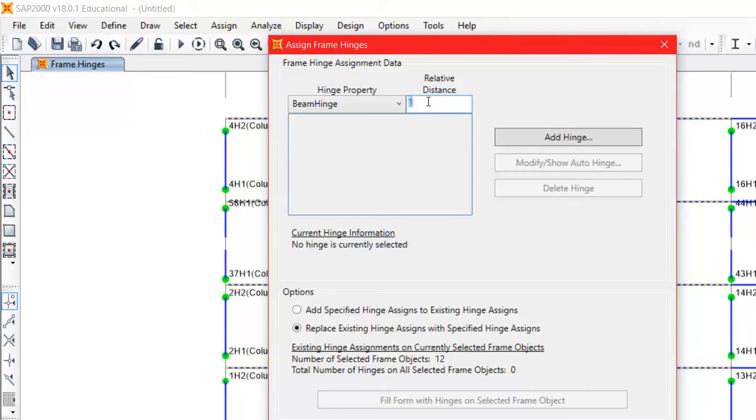So if I have the column like this, and I have the center line, and I have the beam, and I have the RBS rotation somewhere here. If I look in the plan view, it's something like this. So I have the depth of the column. From this point, I need to measure this distance to the center of the RBS. So how much is x? You have this parameter a, right?